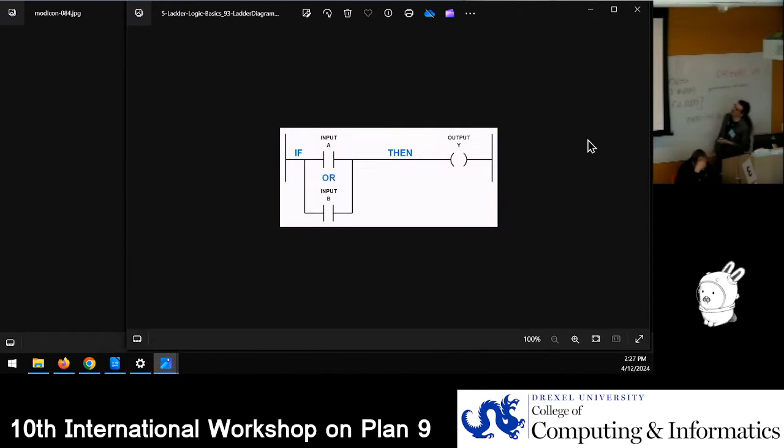It's pretty primitive in the sense that it represents a ladder schematic diagram that was used in industrial control for electromechanical systems, where you would have a vertical left and right, which represented the positive and negative of your control power. Then you would have power coming in on the left, and then a set of contacts. Here we have an OR set, so if A or B is on, then output Y would be true. This is a rung, and you can have as many contacts as you want. There could be comparison contacts, which could look at variables and so on.